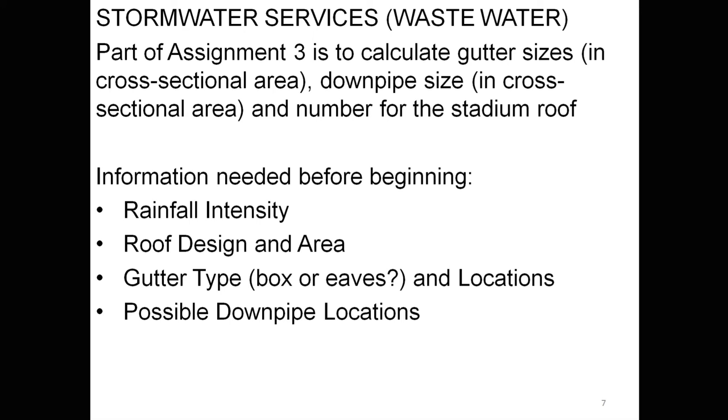Okay, so in many of these cases, if we look at the examples we have, a lot of the roof material itself actually acts as the gutters. So when you've got those kind of folded membrane roofs, it is actually the valleys of those folds that act as the gutters and take the water away. So all that water goes to a certain point, and then from there it needs to be channeled off the roof or channeled to a different place and then off the roof. At which point it may be collected or it may just go into the main stormwater.